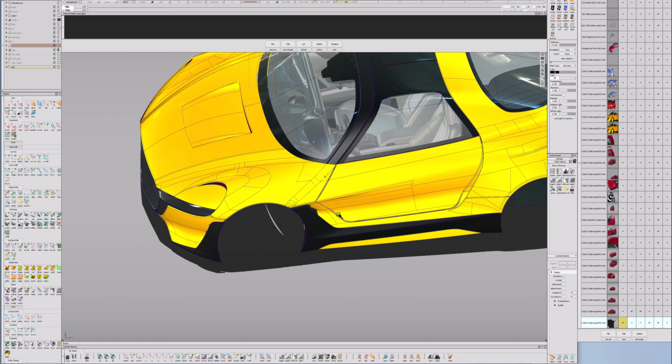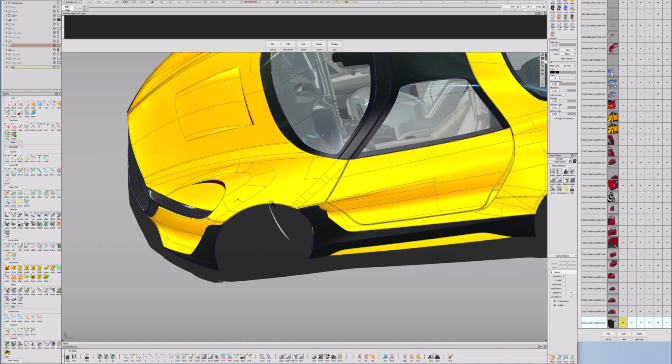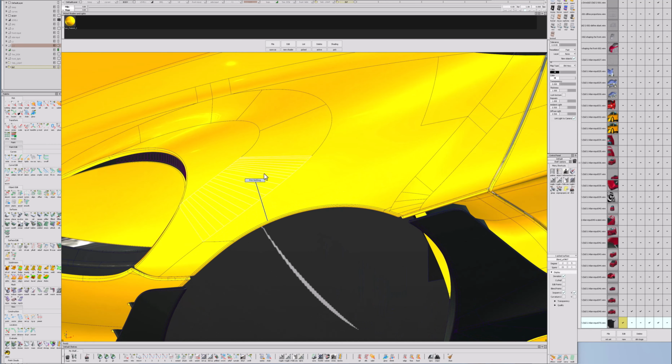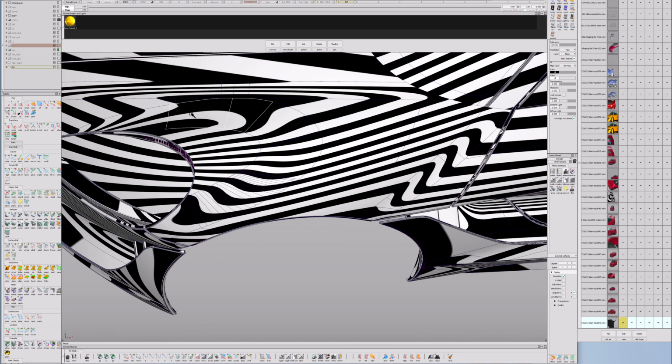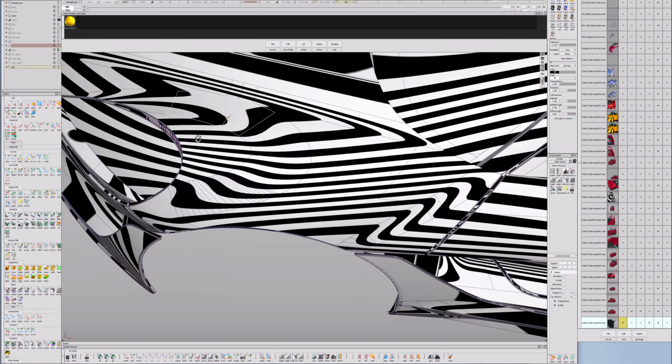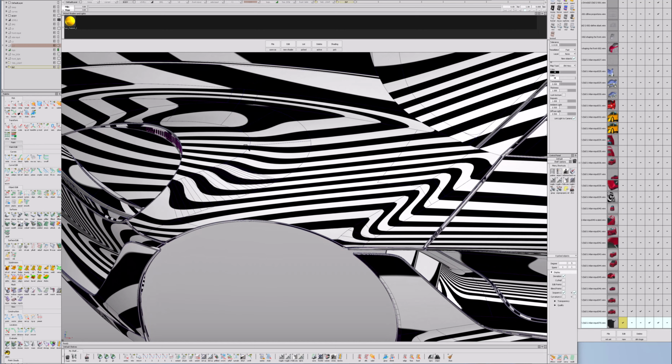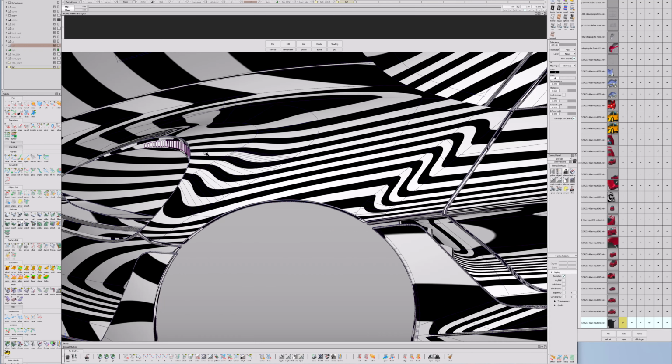I stopped doing A-class. It's a waste of time. Look, what I care about when I model for myself now is only highlights. If the highlights and zebra look good, it's okay for me, and it looks good. If not, like here where it was dirty, of course I go clean. I worked with individual CVs. I tried to clean the area without any bad highlights. But if it works like this with spans, I keep it.